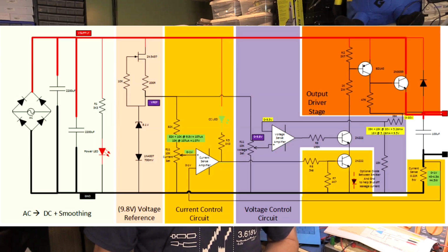And at the end of the day, we're also going to look at a slightly different technique for controlling the MOSFET, because in other videos that you guys have seen, Martin Lawton on his YouTube channel is working on a student power supply, and one of the things that you'll see there is, in order to have the current limiting and the voltage limiting work cooperatively with each other, they're using a pair of transistors, open collector, to dominate either the constant current or the constant voltage, and neither of them can actually push the supply high, but they can pull it low to drive the output stage.